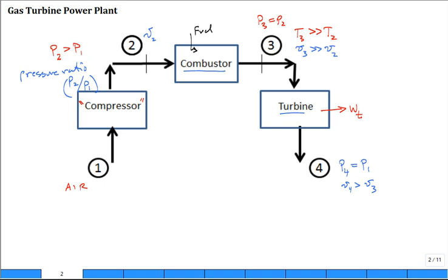The compressor, there's a number of ways to write it. You could put the work coming out of the compressor, and you know that this has to be a negative quantity because a compressor is not a work-producing device. That's staying with the sign convention, or sometimes you just abandon the sign convention. True? What about the combustor? That fuel is coming in and it's burning. There's a large heat release. True? That's how you get much higher temperature coming out.